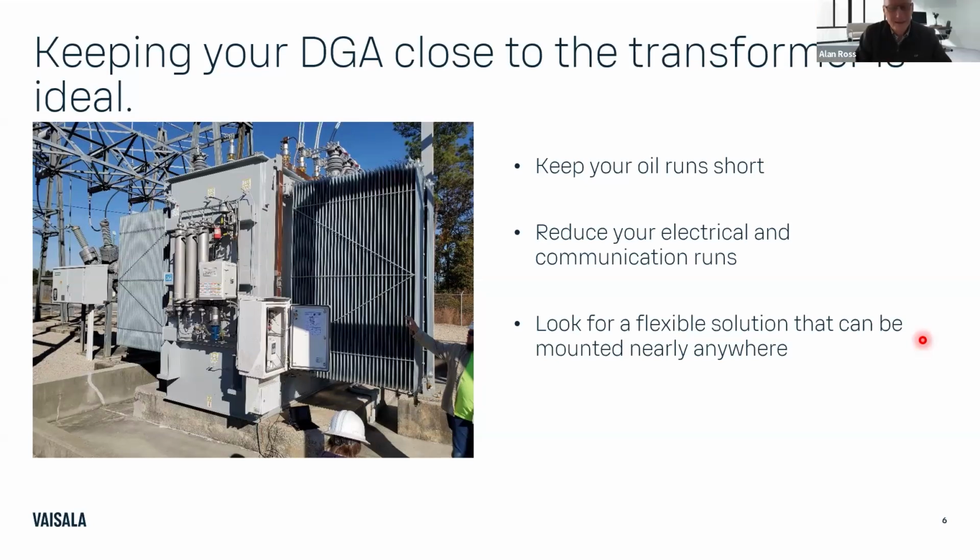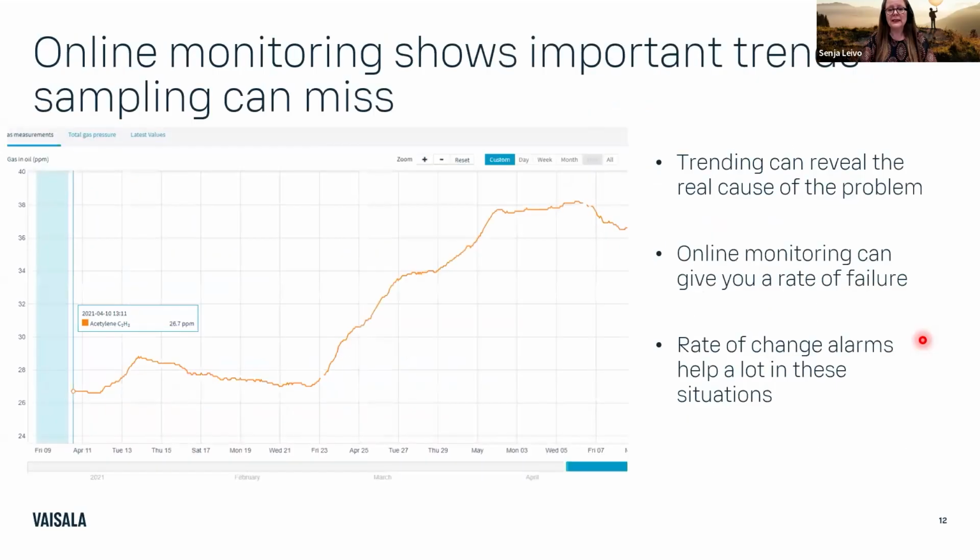95%. Yeah. So if you look at your whole fleet, let's say you have 100 units and you took that 95th percentile, you look at your top 5% that has the highest levels or most different, then you can focus on those. That's my general recommendation on how to look at that. And then if there is a clear indication, like for example, Lee was showing this example where the acetylene was quickly increasing, you may want to use some electrical offline methods to understand where this comes from.